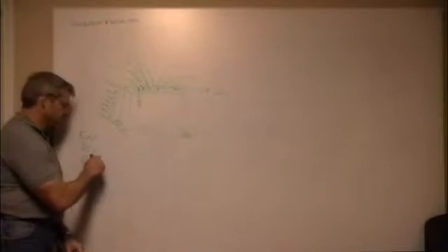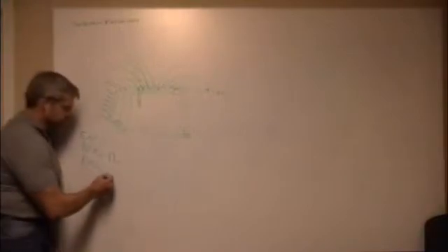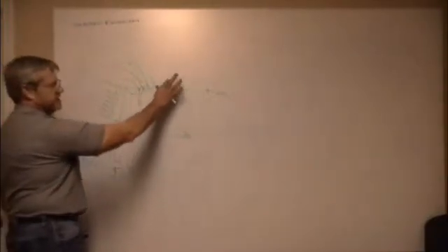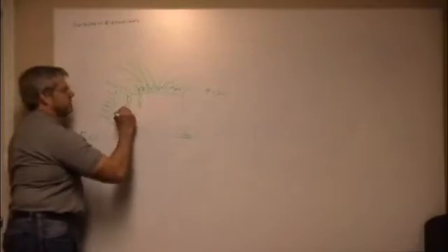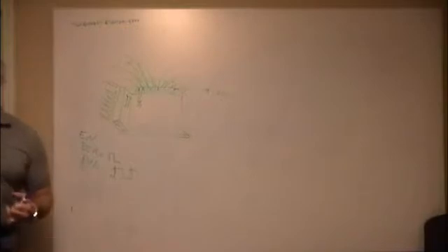The direction command, they're digital bits, so it's high and low. One way causes it to turn clockwise, the other one causes it to turn counterclockwise. It's the only difference. And then the pulse, I think it's on every rising edge. It makes it go one step. And in here's the controls that handles it, does all the phasing, and it's got a switch bank here on the end that you can choose the current, your drive current.